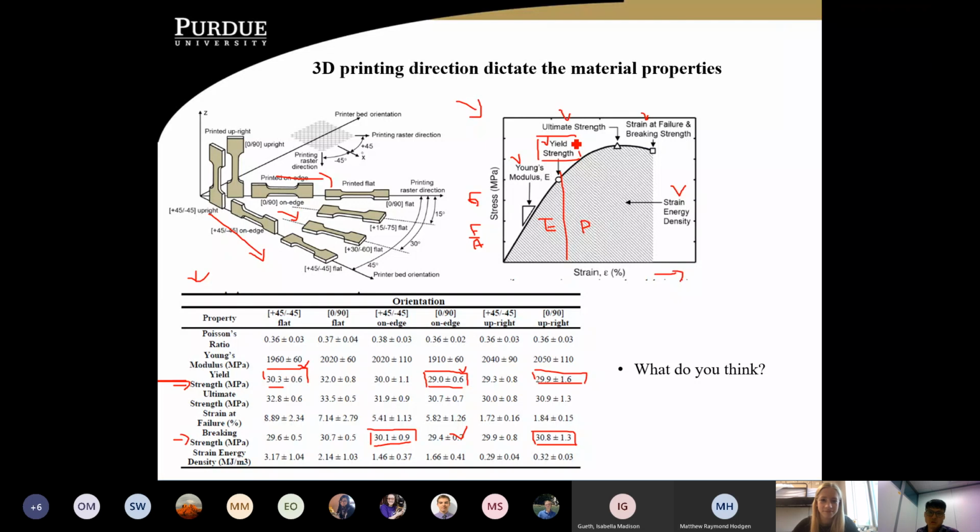Let me give you an answer. No, it will not break. This gesture I'm doing right now is fatigue, but the table will not break. The reason is that it has not surpassed 75% of the yield strength. Now, 75% does not fit every material, but it's a rule of thumb. So just times 75%, and if it surpasses that barrier, then you need to start doing a fatigue test. If it's low, like what I'm doing, don't bother, don't waste time.